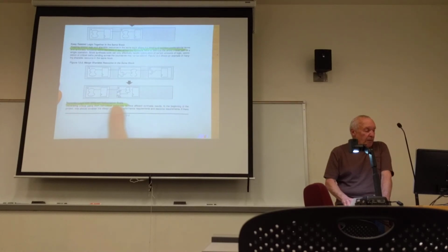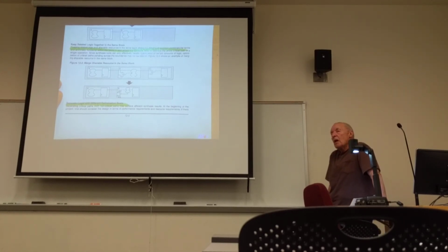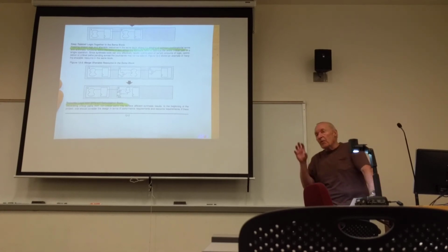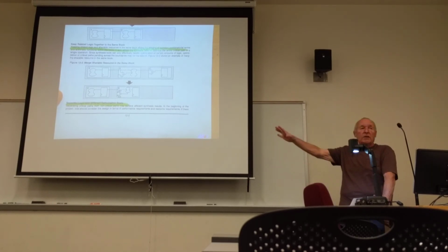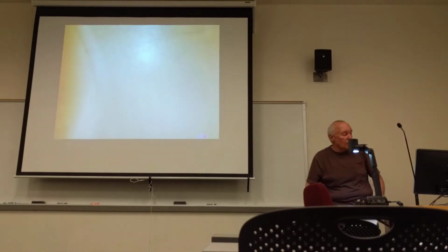Separate logic with different optimization goals. In some cases, you may want to optimize a circuit for speed. In other cases, you may want to optimize it for area: how much space is going to be required on the silicon to implement it. If I have different combinational blocks, one is supposed to be optimized for speed, the other for area, don't put those in the same block. It makes it more difficult for the synthesizer to meet your optimization goals if they're in the same block.